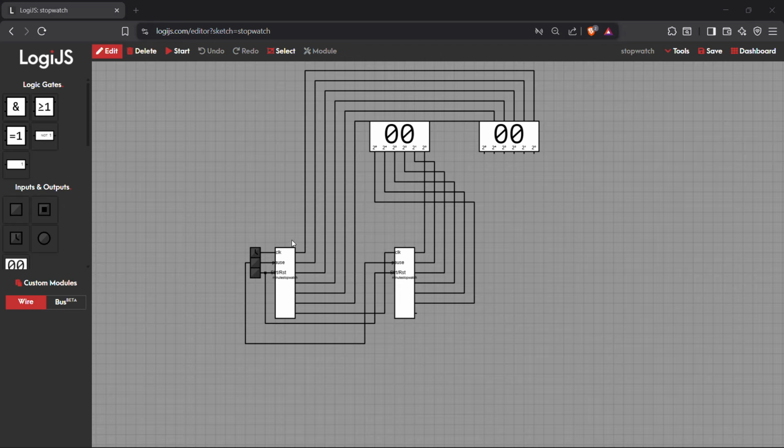This is based on the counter logic which is made using JK flip-flops and some basic logic gates. Here I have used two modules. These modules are the same, cascaded upon each other such that the reset signal from this module is used as the clock for the second module. Each module has to be given a clock, a pause button as well as a start/reset button. The clock will provide the impulse such that it will increment the counter by one for each second.